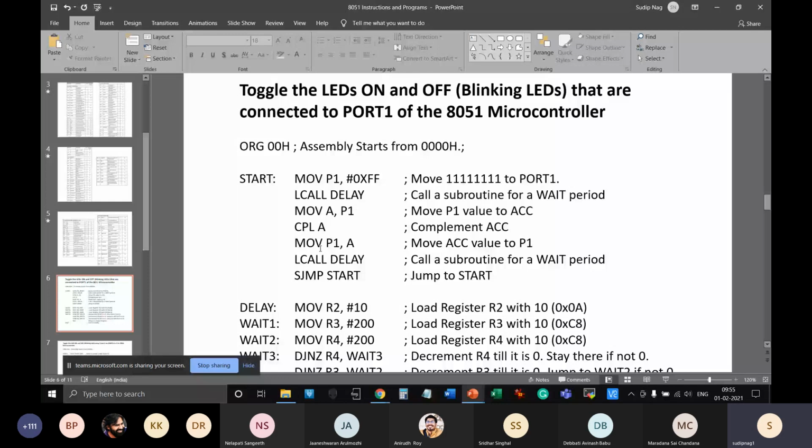C is a high-level language, and you can write C code for a microcontroller, and the compiler will generate code similar to assembly in the background, and from assembly, it will generate opcodes and a binary file, and that binary file essentially gets stored in the program memory for execution.